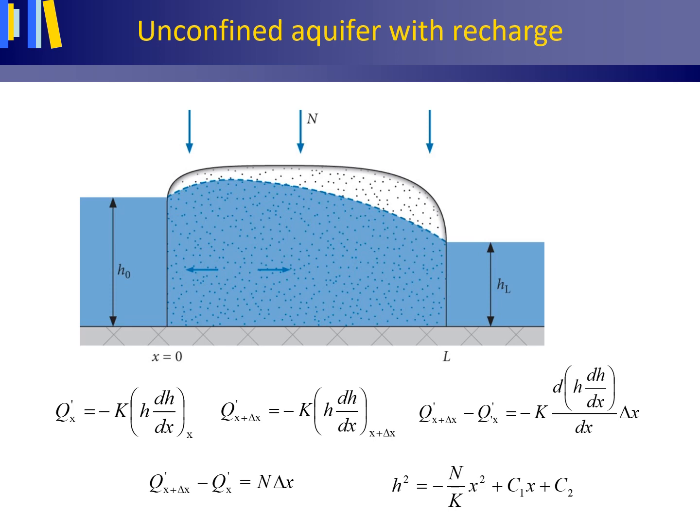This figure shows steady groundwater flow in a recharged, unconfined aquifer bordered by two parallel, fully penetrating streams, but with different water levels, as for instance in mountainous areas. The aquifer is homogeneous and isotropic, and also here the horizontal length of the aquifer must be at least 5 times larger than the saturated aquifer thickness in order for the Dupuit-Forchheimer assumptions to apply.